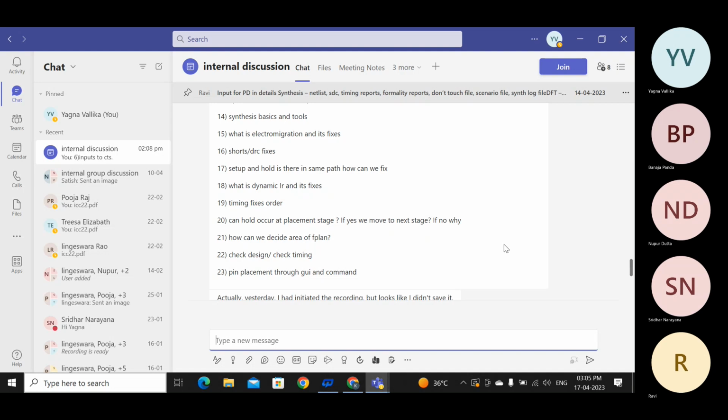See, if both the exact clock path is same for the setup and hold, this also can happen because if your cell delays are varying across the corners, like 7x, 8x, cell delay in setup corner is 100 picosecond, but in the fast corner it's only 10 picosecond. Okay, that's one reason, and that can cause very fast crosstalk. So I've already told you crosstalk, clock skew, right?